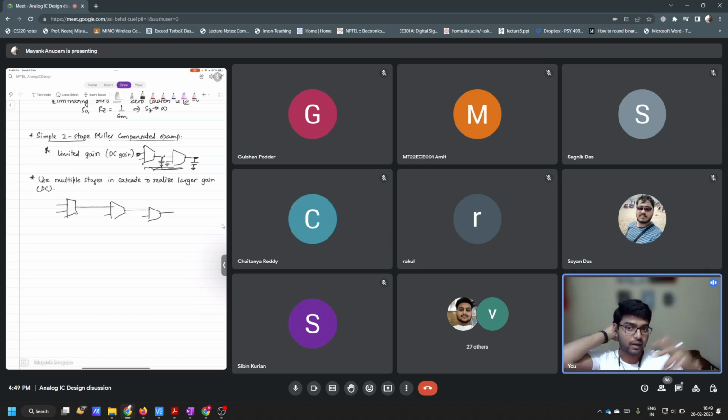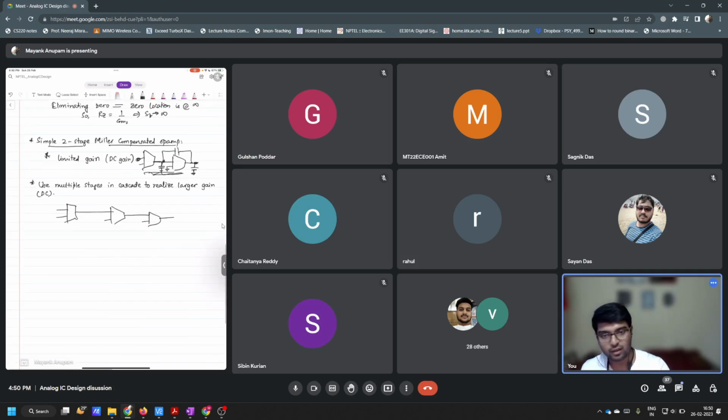It adds two poles, and these two poles simply mean there are two delay elements in the circuit, and delay in the circuit is not good. It will add instability to the system. So that is why we added compensation, to make sure that this delay does not harm us. We added this capacitor to make sure that the overall system is stable. We did some pole splitting, and everything is fine.